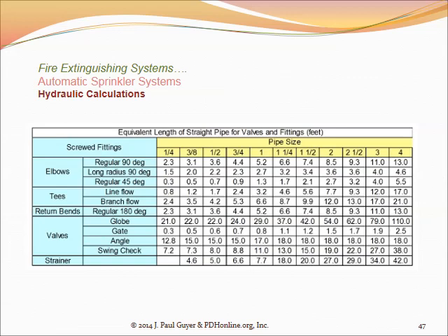But the vast majority of the piping is probably going to be 1.5, 1.25, 1 inch, and finally 3/4 inch. And so you do a preliminary layout and say, okay, I'm going to assume 2-inch pipe from here to here, and then it necks down because some of the water is discharged in other branches, and it necks down to 1.5 inches, and then down to 1 inch, and then down to 3/4 inch.